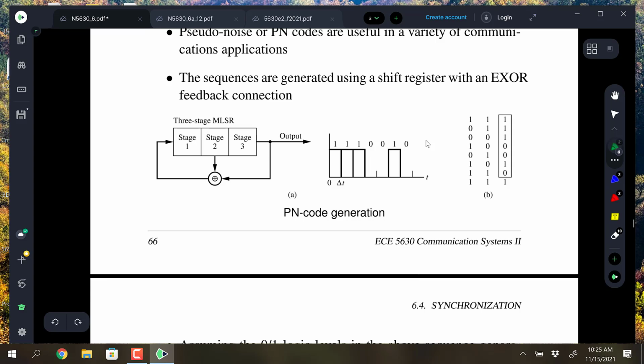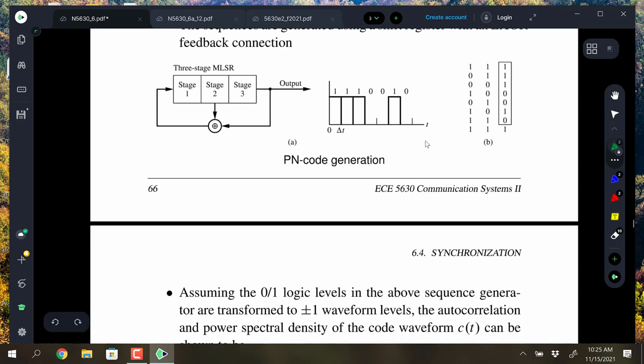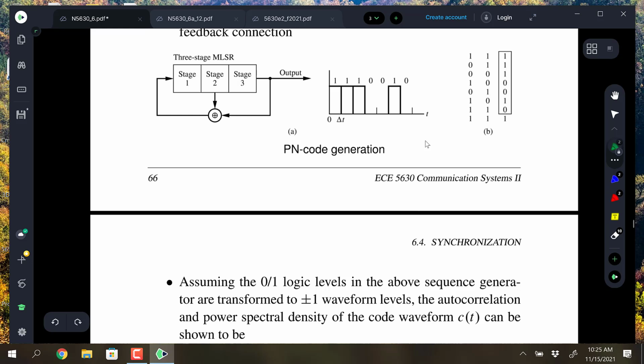So a little discussion on that. Three-stage shift register, just as a starting point. What is an M sequence? It's a feedback shift register where you have an exclusive OR between two or more taps, and you use that to form a feedback. So in this three-stage register, this particular implementation of the M sequence is stage 3 XORed with stage 2 fed back into stage 1.